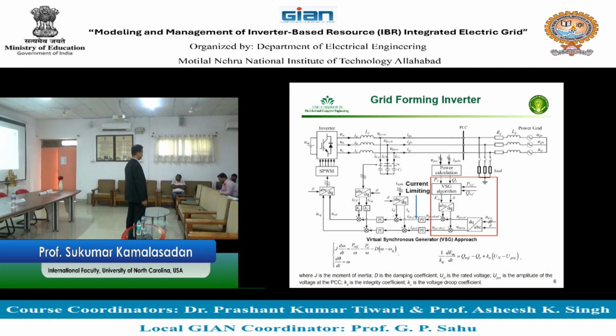You are virtually creating it. When you do a virtual synchronous generator, what is virtual? What is there? It's a bunch of equations. There is nothing other than that. You generate voltages and everything from the inverter using a bunch of equations. That's why it's called virtual.